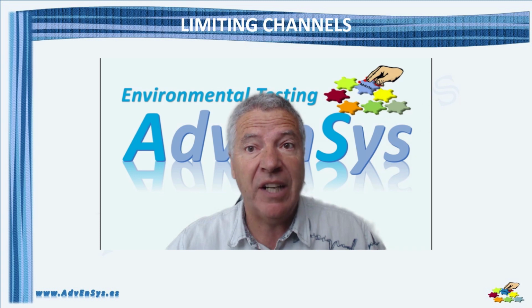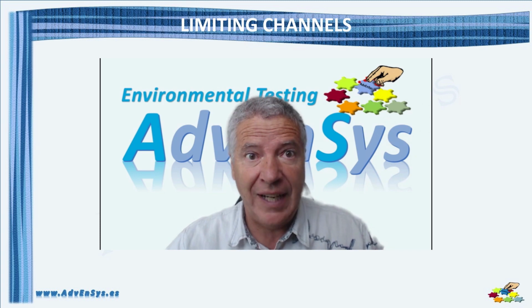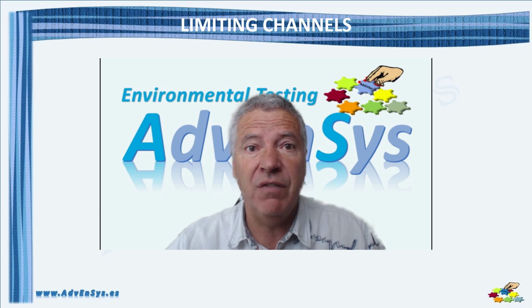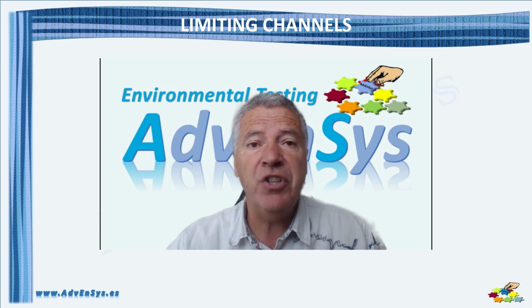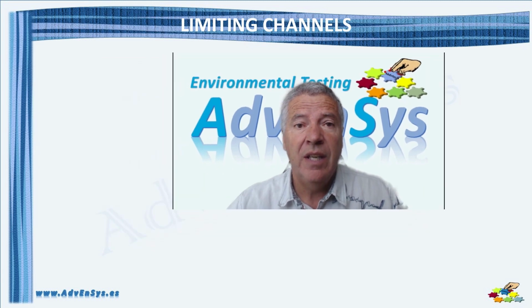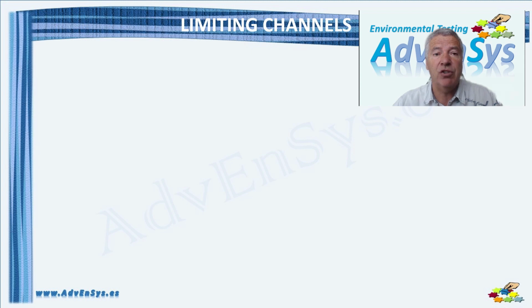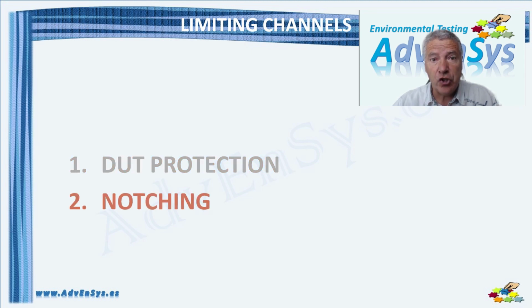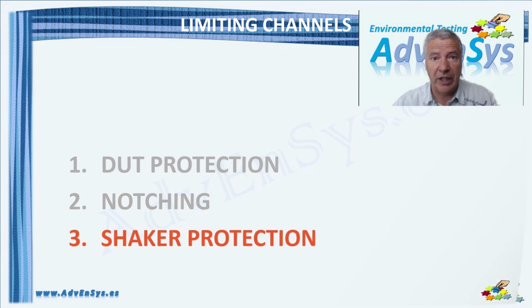Most of the controllers in the market allow you to define a response channel as limiting channel. A limiting channel is a response channel, but if the vibration level that it is measuring reaches a predefined limit that we have programmed, it takes the control of the test to avoid that the acceleration at that particular response point exceeds the limit value. Let's analyze three applications of a limiting channel: DUT protection, notching, and shaker protection.